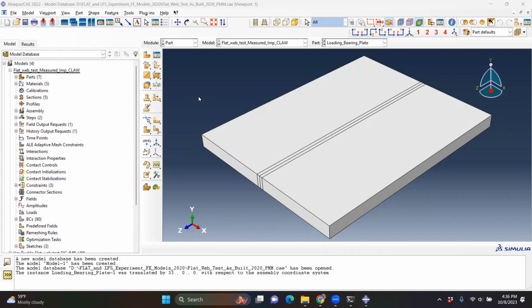Because of the thickness of bearing plates, we usually have to model bearing plates as solid elements. In the previous tutorial modeling videos, all of our modeling has been done as shell elements. When we do bearing plates, we're going to model them as solid elements because they are very big in terms of their thickness ratio. So we are required to model them as solid elements to get the proper behavior in the analysis when we're doing finite element numerical methods.